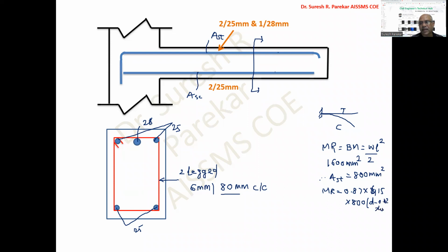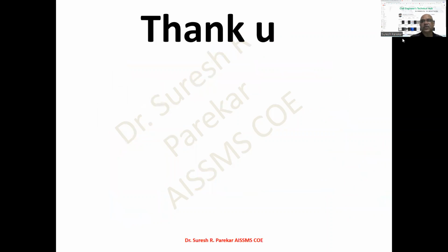Now, as it is a doubly reinforced beam, it becomes a little lengthy, because we again have to add 50% curtailment of compression reinforcement. Actually in doubly reinforced beams, we avoid curtailment and keep the steel as it is. In the exam this was asked, so you have to go for this one. I will skip that step. Now I will stop here only. So thank you.